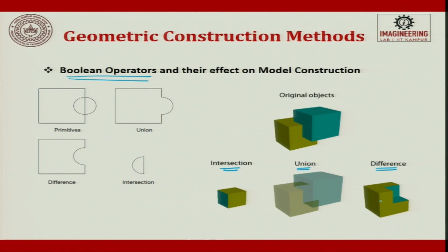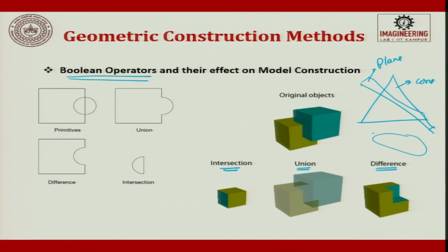So, what this means to say is, rather than drawing a component fully from scratch, you use these solid model primitives which are available and try to smartly use the Boolean operations to get the profile or the feature you want. For example, if you wanted to generate an ellipse, all you have to do is pull a plane option in the model, pull a cone option, and try to place it at some place and say A intersection or A union, whatever it is you try to define, and then the profile that gets generated is going to be an ellipse.